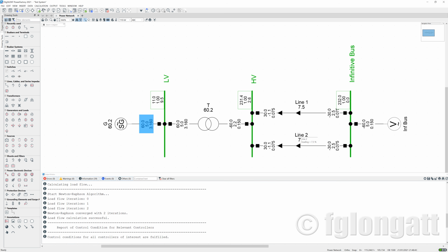Okay, right now you can see how the arrows are moving, and this is indication. You can see that the reactive power is coming from the infinity bus bar to cope with the reactive power losses in this area, but this generator is producing 5.0 MVR to cope with the voltage regulation here. Okay, and finally, I would like to do something else.